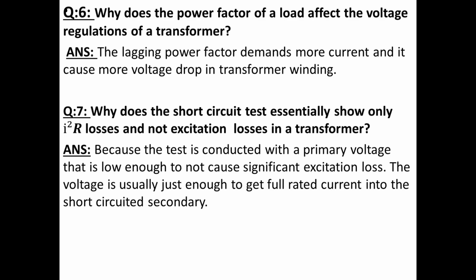Number 6. Why does the power factor of a load affect the voltage regulation of a transformer? Answer. The lagging power factor demands more current and it causes more voltage drop in the transformer winding.